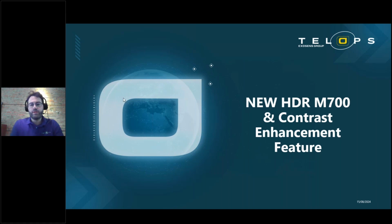Great. One little note before I let Joe talk about the new contrast enhancement feature and the new HDR M700. Once again, about the multispectral cameras, I will say there's no point in using the HDR feature on multispectral cameras. What you can do with a multispectral camera, yes, is use a specific filter wheel set to have a different set of filters that are using different neutral densities. So you have different exposures through the different filters, and that way you can recombine those images manually in the process and the software thereafter.